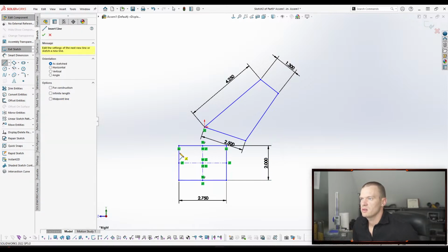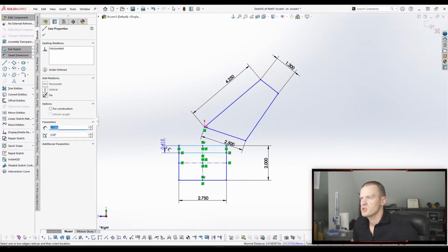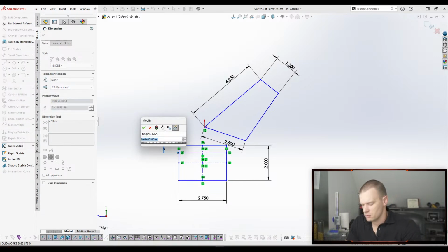Also start laying in things like our material thickness for the sheet metal. So this is 197, and I know it's aluminum. So we need to figure out what gauge of aluminum is 197.